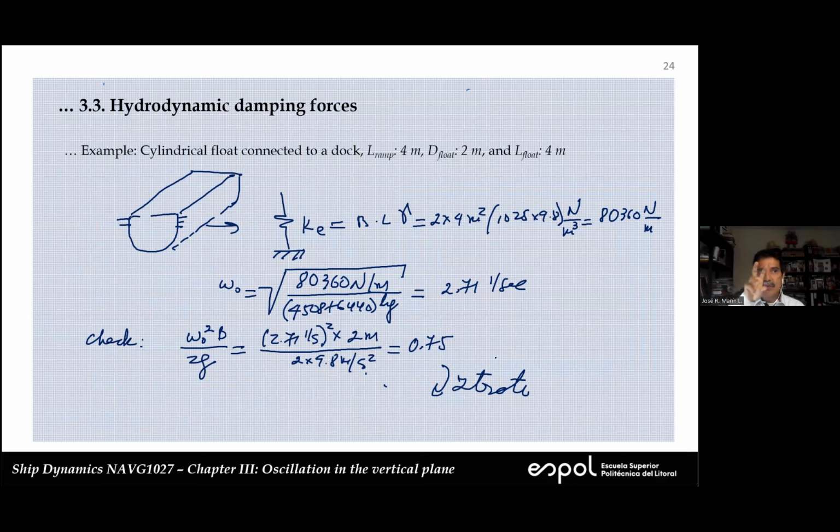The two natural frequencies, heave and pitch, will be mixed together because they are close, and this is a problem because there is a change in excitation wave amplitude. But that's usually the way we do it. We don't calculate natural frequency directly. What we do is we calculate the response, and in the response, with these increments, resonances, we identify natural frequencies, because this takes too much time.